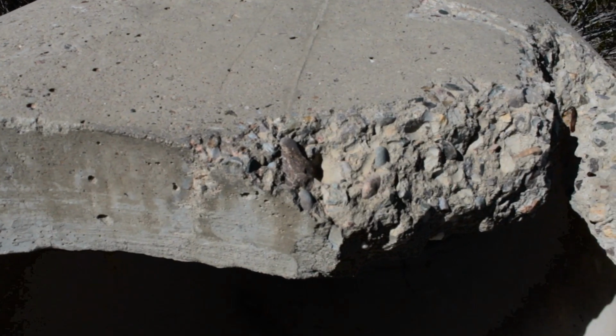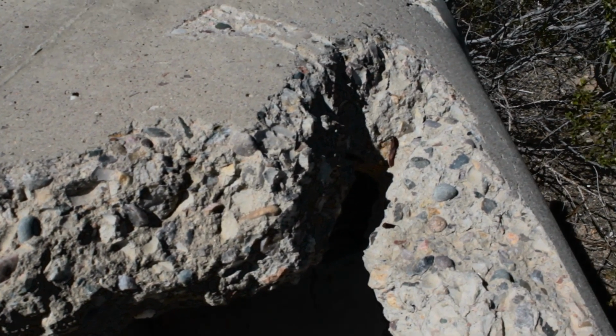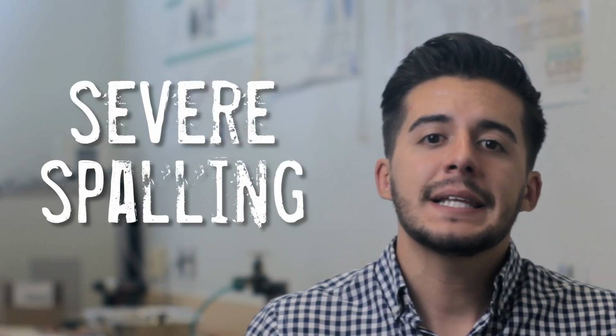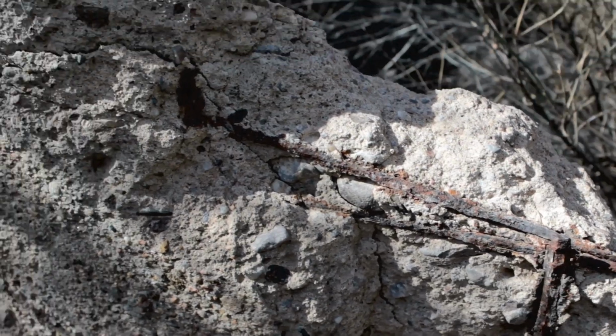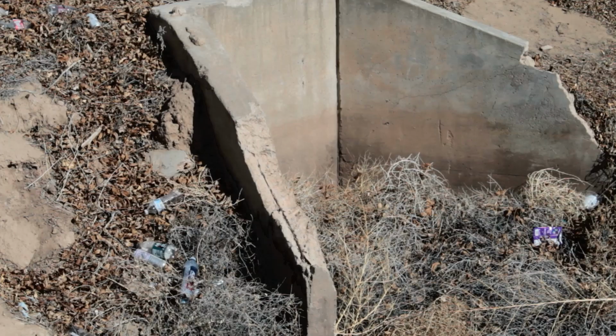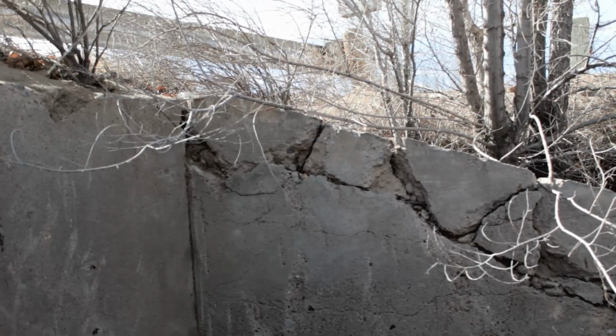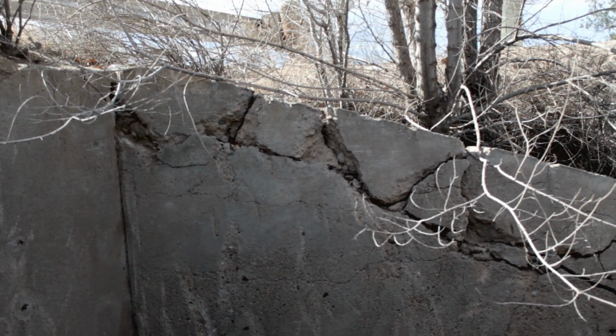For concrete culverts, you can select circular pipe damage, spalling, that is when concrete chips or flakes away from the structure, with no exposed rebar, or severe spalling when you find exposed rebar. Spalling and cracks on the head walls or the apron, and severe cracks that are more than 1/4 of an inch, and others. If you're inspecting a group of culverts and you find different physical conditions, select the worst.